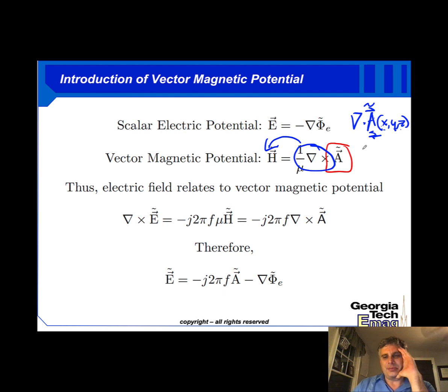And that's very interesting because, in a way, we have only partially defined our vector magnetic potential, a vector, by saying its curl must be equal to H. So this really means that if we know what the H field is, there are actually an infinite number of A vectors that can be taken the curl of and still make an H vector that we desire.